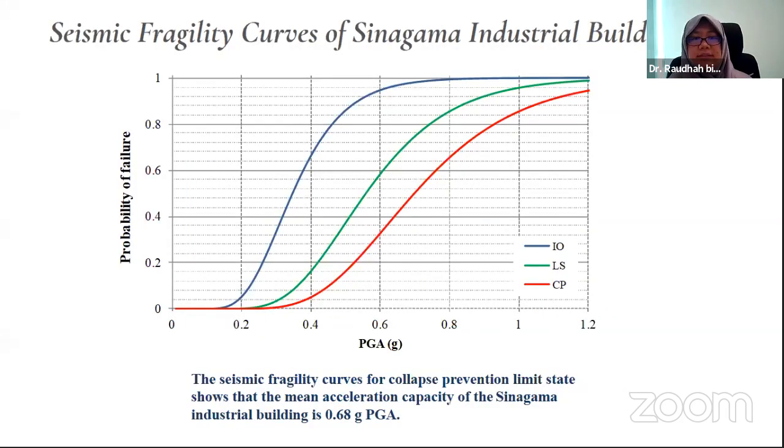It seems that the building has of course been constructed well because they knew initially that it is for high importance. So I'm sure that's the main reason we found that the capacity is very high. From the vulnerability, you have to develop the seismic fragility curve of the industrial building, because we want to combine this with the industrial facilities assessment in the form of fragility curves.